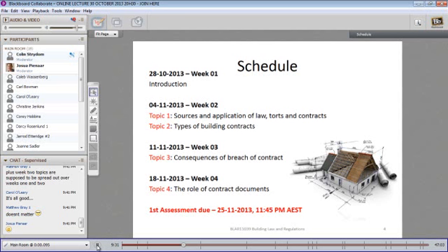Another section that's still part of the importance will be a bill of quantities. It's not always a part of a contract, but it's usually set up by a quantity surveyor, and that's just a basic setup of all the items from walls right through to toilet or plumbing fixtures, the value of it. It could be 4 toilets, and the contractor just has to provide a fee for each, and then that gets multiplied, or it could be a square meterage of walls, and so on and so on.